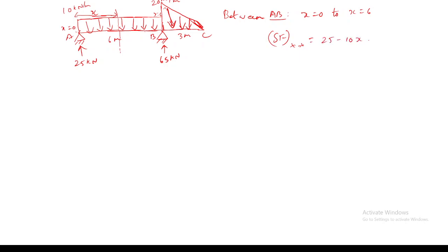I will explain how we are getting it. In our earlier problems we have been seeing point loads, and with respect to point loads we have only shear force diagrams which are a kind of rectangles. But here we mostly won't be having rectangles. Since this is a uniformly distributed load, the procedure is like this: we have to take a section from either the left hand side or the right hand side.